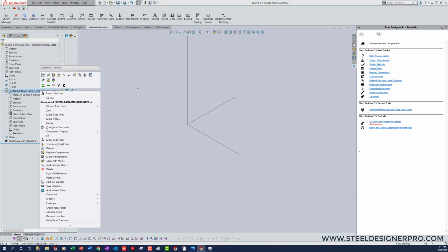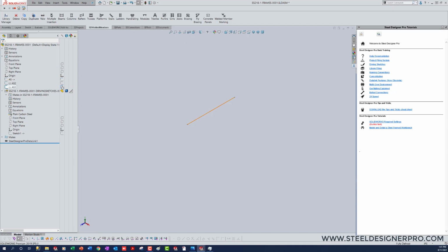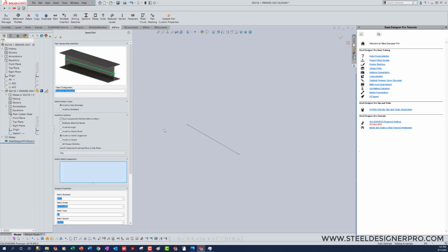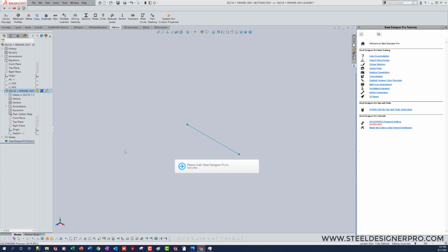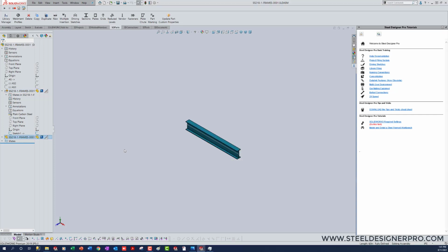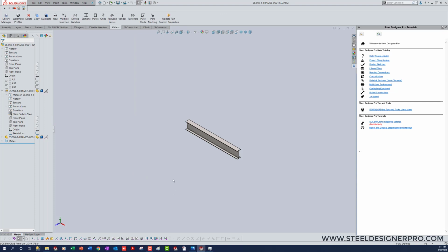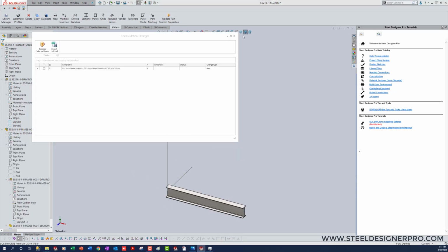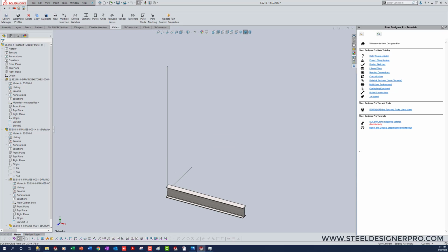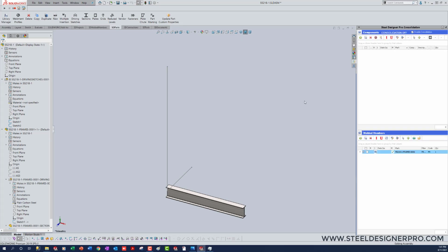So in the driving sketch, let's hide those. Let's do this. We're going to just grab a part and drop a section on here, and we do not care what that section is. And we'll edit that attachment sketch, delete that equals relation, and we're going to turn off consolidation.